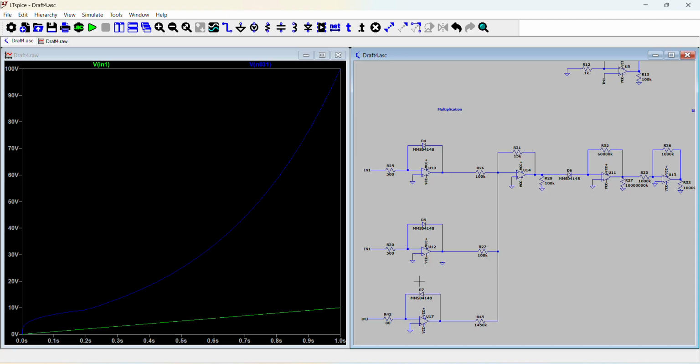So what I did is I added another circuit to basically subtract away some of this error. Because when you log A divided by B or log A times B, if you add that out, it becomes log A plus log B or log A minus log B, right? And so that error in the minus or plus log term, you can cancel it out using a third log that minuses them.